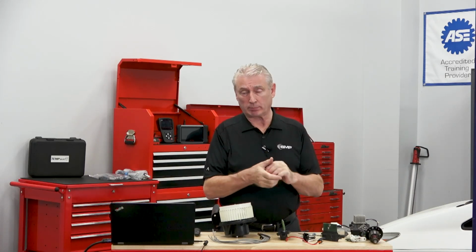In general, I do not recommend using a brush type motor if the vehicle came originally with the brushless motor. Brushless motors are all electronic. They're very quiet. They don't generate a lot of electrical noise. Using a brush type in its place could generate electrical interference onto the dash that could interfere with the communication circuits and so on. So in general, I do not recommend using a brush type. If a brushless option is available, I would highly recommend sticking with the brushless replacement.